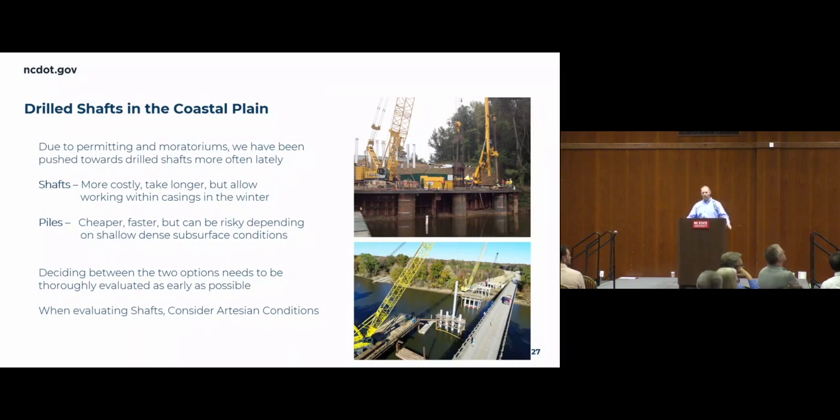There's a lot more issues potentially that can go wrong. But again, it allows us to continue to work. Piles, when we can do them, are obviously preferred. Generally, it is going to be a cheaper option, a little bit faster, less risky, depending on the conditions. But sometimes we have subsurface that will give us a problem if it's not down deep enough to where our minimum tip is. Trying to get through a dense sand layer or something like that can cause problems with pile driving, and so that may lead you to drilled shafts or maybe some kind of pile excavation, pre-drilling, spudding.